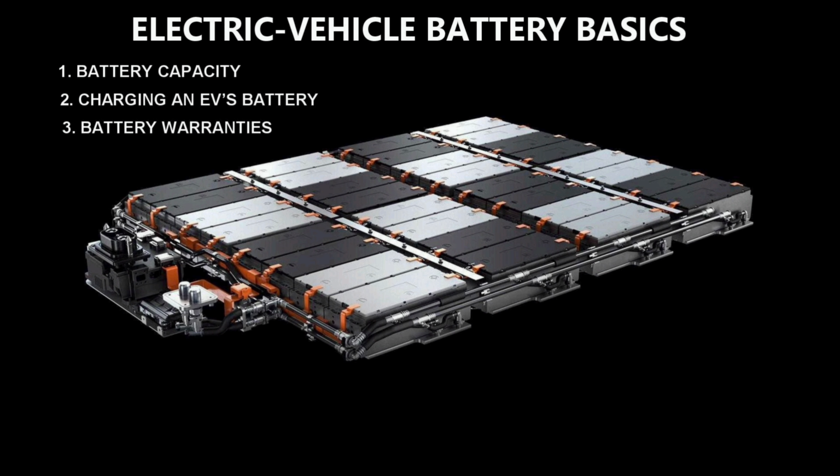Choosing an electric vehicle with a higher kWh rating is like buying a car that comes with a larger gas tank, in that you will be able to drive for more miles before needing to fill up. But be aware that, because of the way electric vehicles work, we will never actually have access to the full battery capacity. That's because the car's management system prevents the battery from becoming either 100% fully charged or 100% discharged, to preserve its efficiency and extend its usable life.